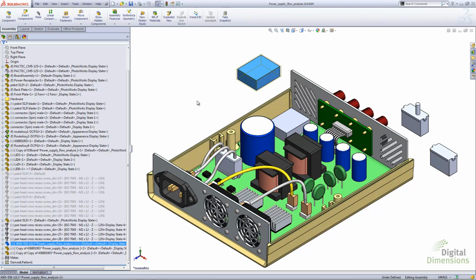And ever since 2010 and later, we cannot change that functionality. So by default, it had part 1, caret, then assembly name. If I wanted to simply rename this to just plain part 1, that is not a possibility starting from 2010 and later, due to changes done internally to the SOLIDWORKS software.